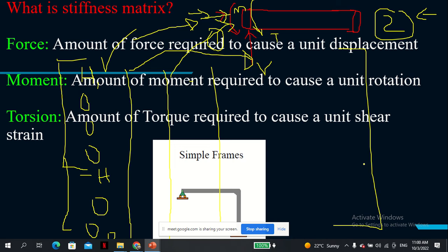However, you are lucky because most structures only have shear and moment. Actually, that's the biggest problem. Shear and moment. In a few cases you will also find a direct axial force, as you will see. So the most complete matrix, if you watch the video, is a 16 by 16 matrix. But in most cases we don't have torsion because we don't design our structures for torsion. Rarely do we do this, and in any case, the software can do this for us.